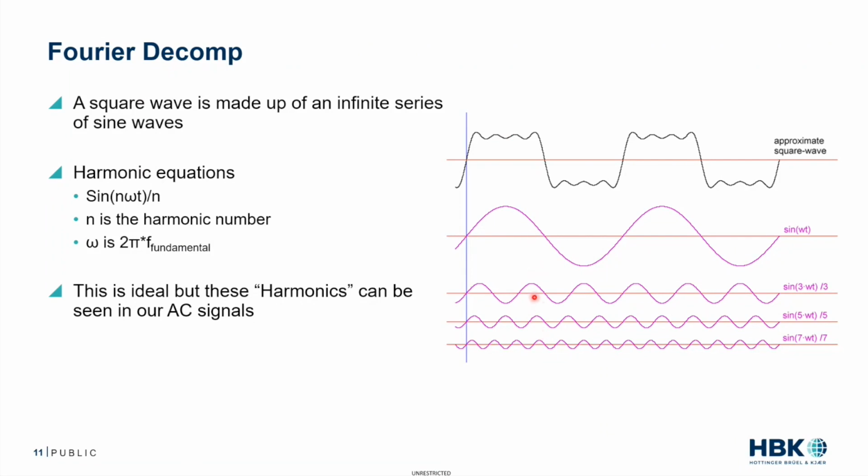But this is really important to keep in mind, because each one of these harmonics, and granted, this is a perfect scenario again, has a phase between its voltage and current. It has its own element of reactive power. And those are getting added in, and those are getting added in, and those are getting added in. So when we talk about reactive power, and also RMS values, we need to discuss the reactive power of what frequency band, the apparent power of what frequency band, the RMS of what frequency band. And this is the difference, and this is why filters become so important.